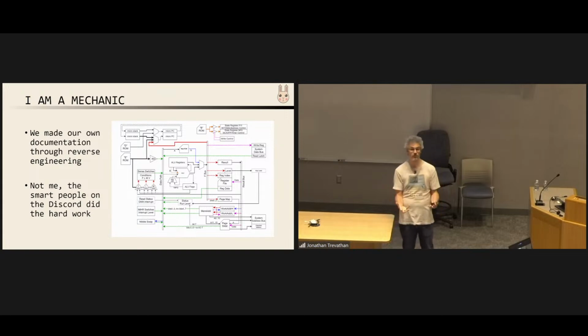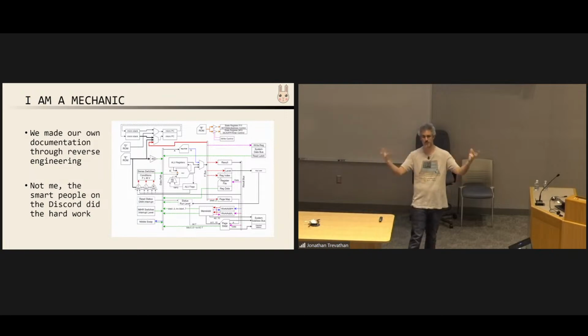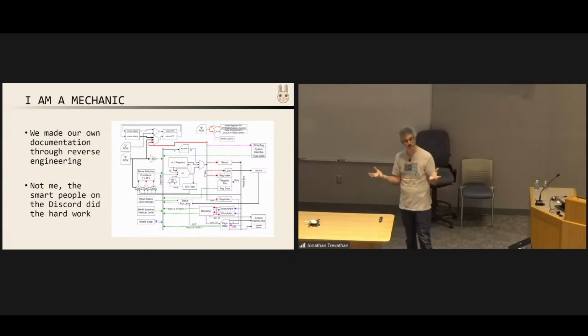And so when I say we reverse engineered the CPU, it's a card that's about this big by that tall with about 85 ICs on it. It's got a lot. It's based on the AM2901, which is a 4-bit bit slice ALU, and it uses microcode. So it has 7 ROMs on there that have a 56-bit micro word, whatever. It's all quite complex. So what we did is we pulled the microcode off of those ROMs. It was still intact. That was good. And we had somebody going through trying to figure out what that microcode meant.